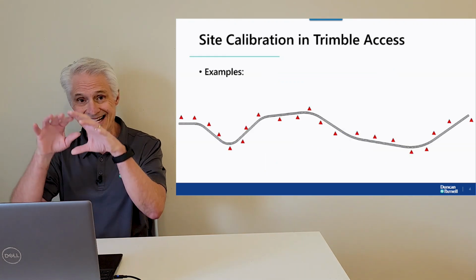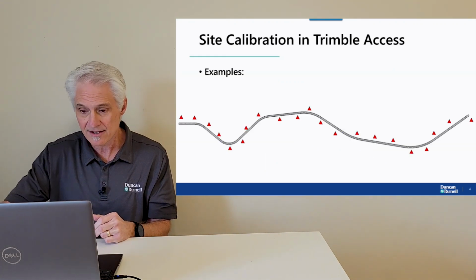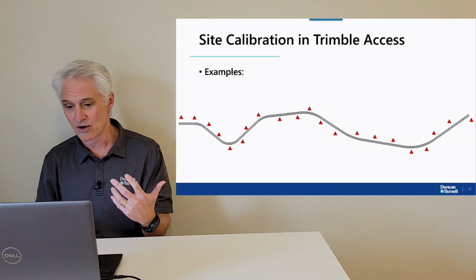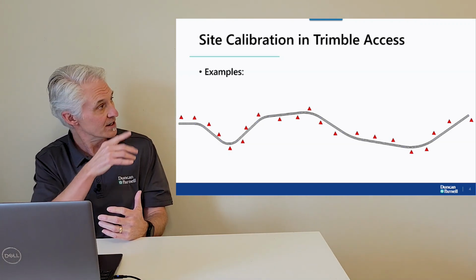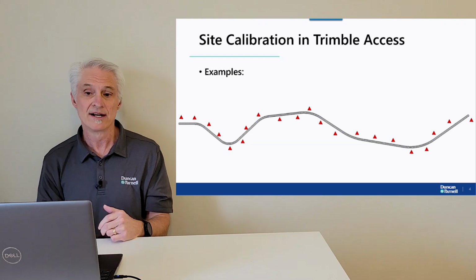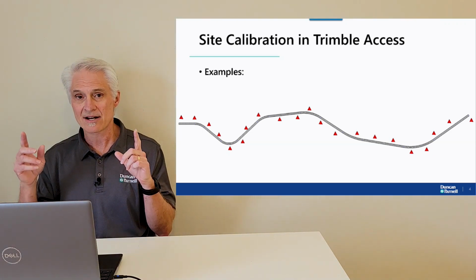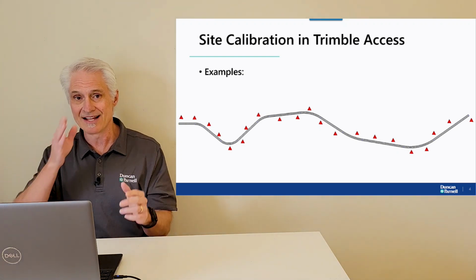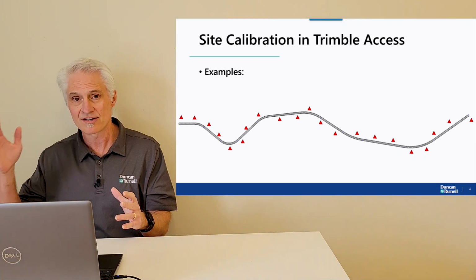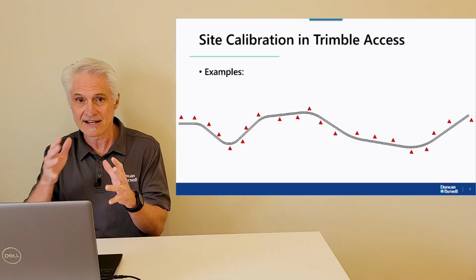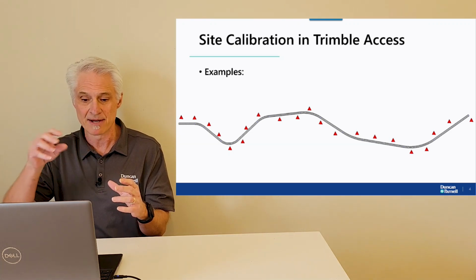So that's a survey site that has control surrounding it. What about a linear survey like a roadway? So here I've got a winding roadway that's got control going all the way down it. You would probably at least want to calibrate to the two end ones and then pick points along the roadway that are evenly distributed. That's going to give you the best geometry.